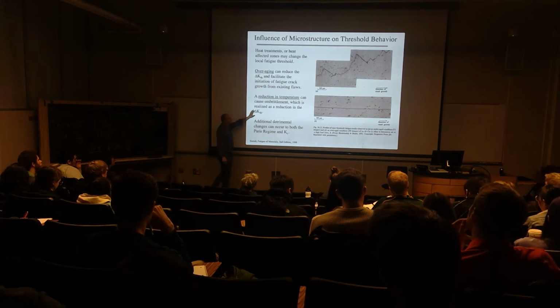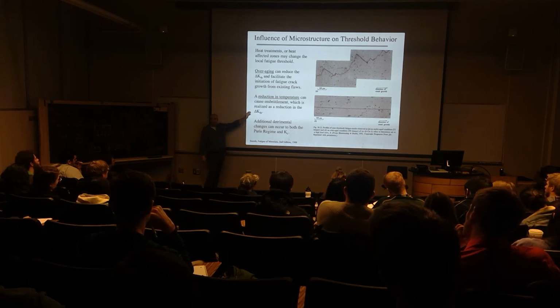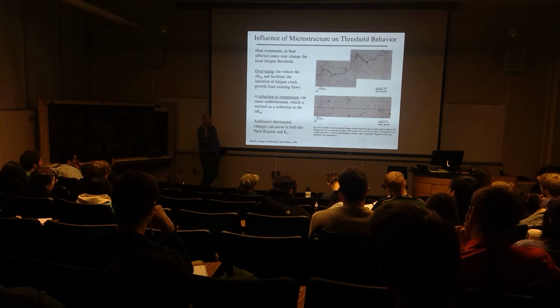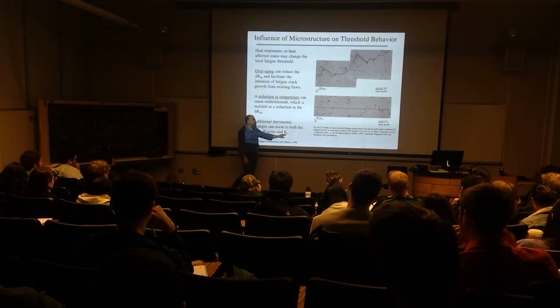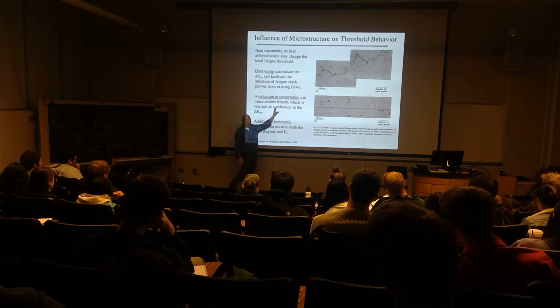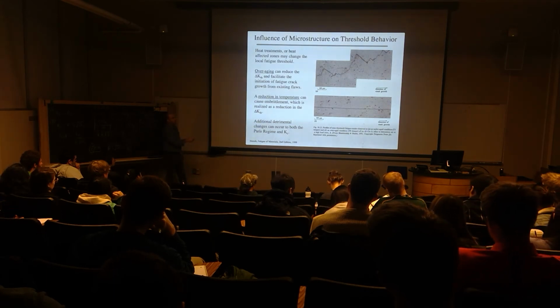The other thing that can happen is we can have a change in temperature. So if we have a ductile to brittle transition temperature for a material and that temperature decreased in the environment, we can lose the near threshold regime response, and our delta K threshold means nothing anymore for that material. So we can have things that also occur in the Paris regime and also the fracture toughness in fatigue, but really threshold effects are most commonly changed by this problem with heat treatment and/or changes in temperature or mixtures.